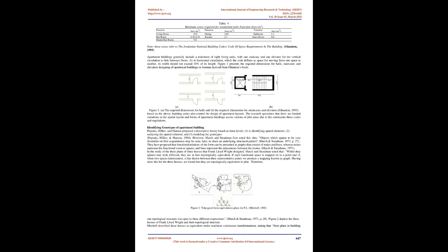Table 1 and Table 2 summarize the regulations for residential land use, including those concerning setbacks, the percentage for construction, and the minimum area required for a plot in each residential zone. Note, these numbers are as per Article number 11 from the Regulation of Zoning and Building of the City of Amman number 76 of the year 1979 and amendments thereto (Greater Amman Municipality, 1979). The maximum allowable floor area is determined by calculating the area percentage of the plot and the area within setbacks. The smaller area is the maximum area allowed for the plot's design.